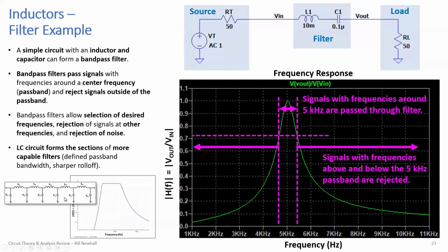And there are filter design tools that you can use for different types of filters: Chebyshev filters, elliptical filters, Butterworth filters. And then you can go simulate them. So if you ever want to build a filter to pass a signal, let's say from a sensor or an audio source, and you want to block noise outside of that band, you can design filters online, and then you can use tools like LTspice.